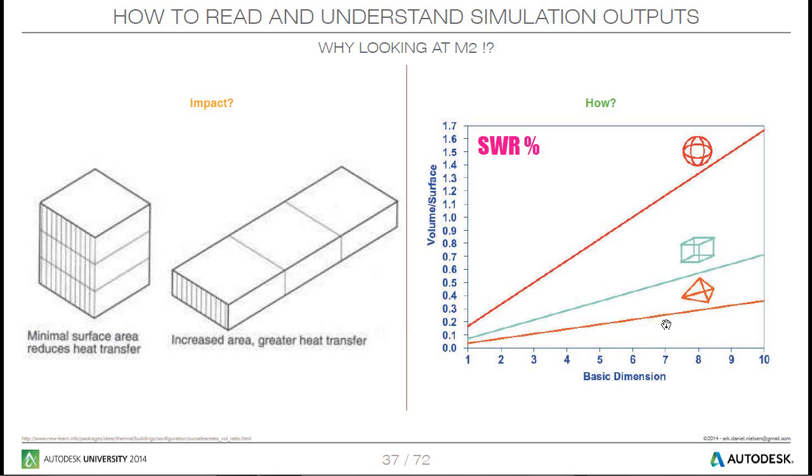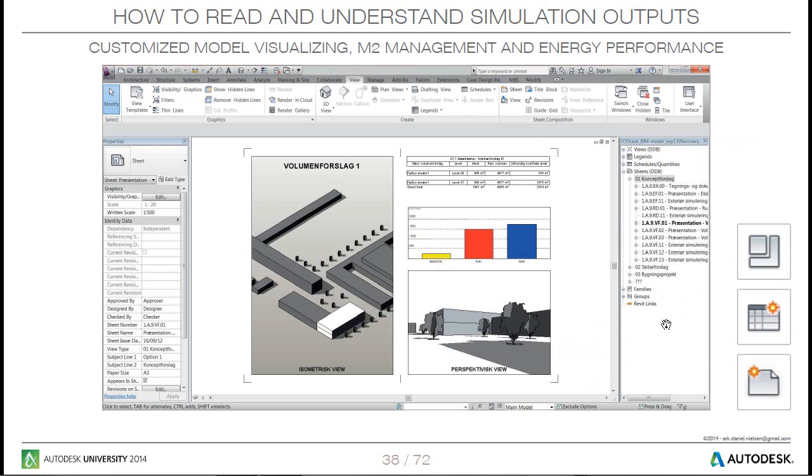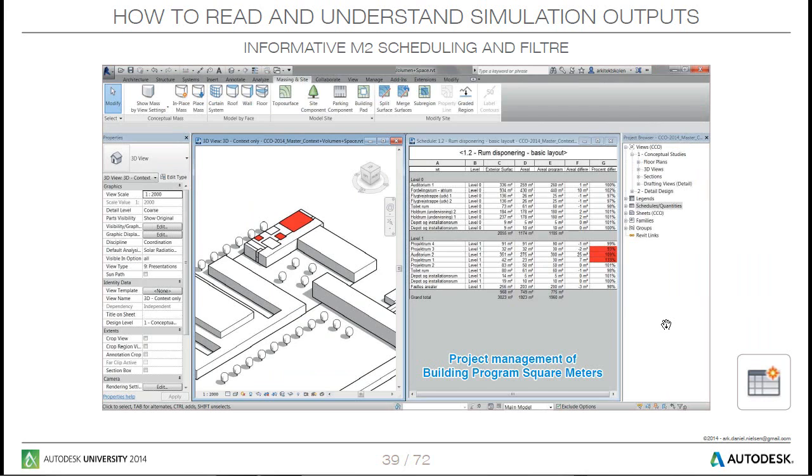And for that we have schedules, and in this case I've used this for a student course to show them possibilities where I actually make my own communication of these results, having built a simple bar chart with the energy number and showing the square meters so I could compare it. I'll show some of the results later on here. Using sheets to set these kinds of things up and keep stuff inside the Revit environment.